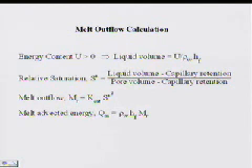You get ice layers developing, and the paths that meltwater takes to actually flow through snow are really complex. So the approach we took was we said we're not going to worry about any of that. We're just going to look at how much water there is in the snow and assume it drains according to Darcy's law for flow through a porous media, and the hydraulic conductivity being proportional to the relative saturation cubed, which is one of the relationships that comes out of the Handbook of Snow. I guess Sam Colbeck's work has established this sort of thing.